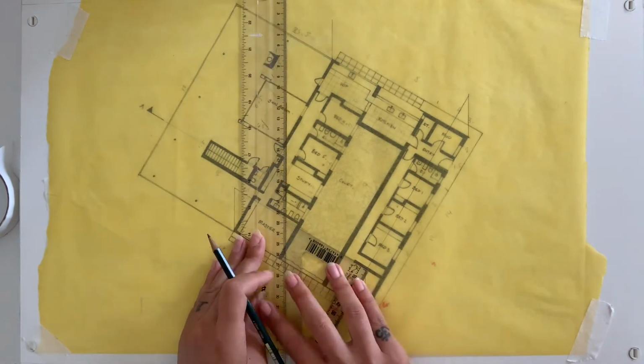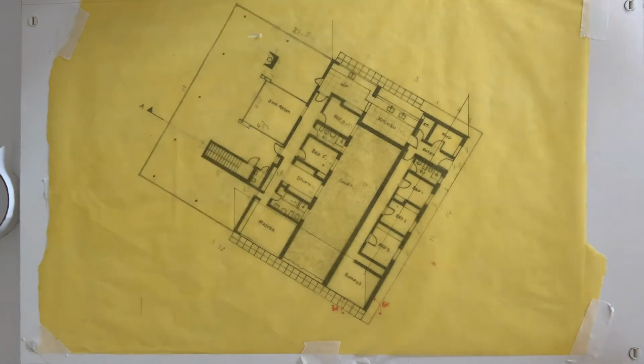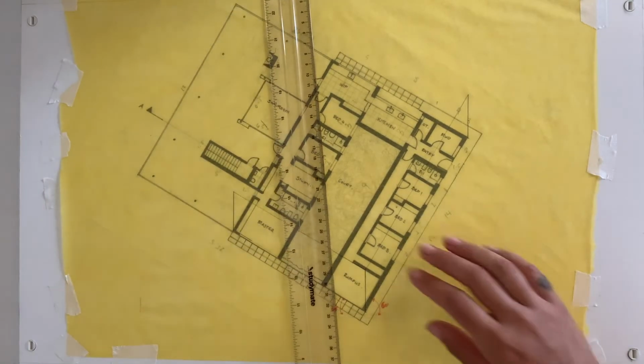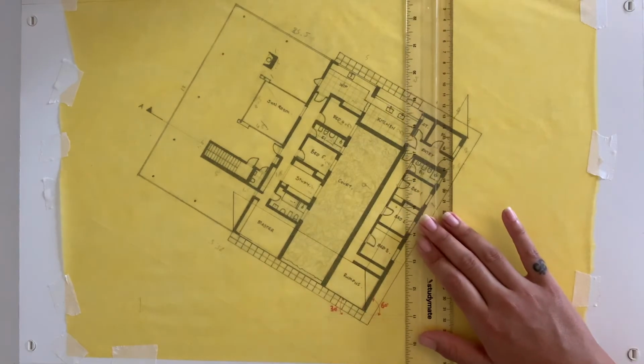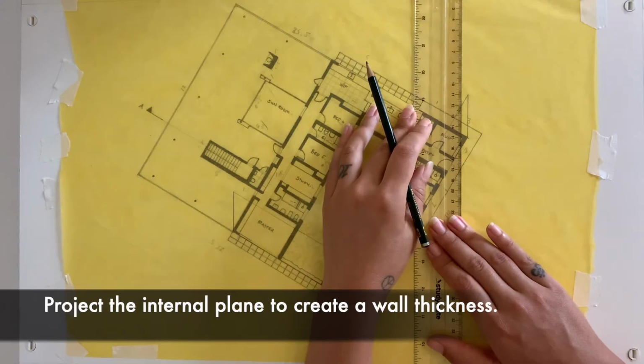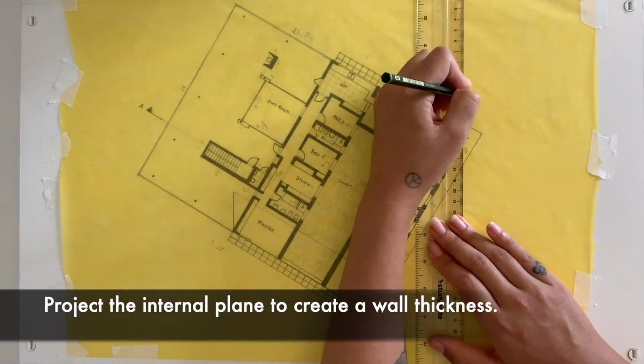So now that I've created these two planes that are facing me, I will proceed to draw the inner side of the wall. This gives a true three-dimensional drawing, giving the walls thicknesses. So I will proceed by just repeating the same process, except I'm taking reference from the inner corner of the wall and then going up at that 4 meter height to scale and just making a mark.